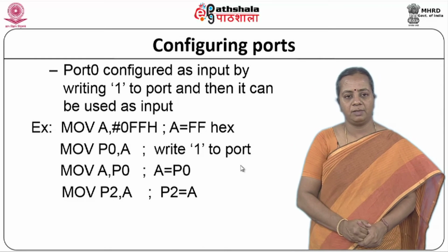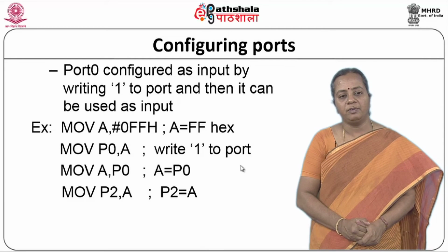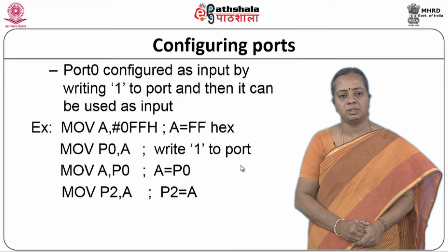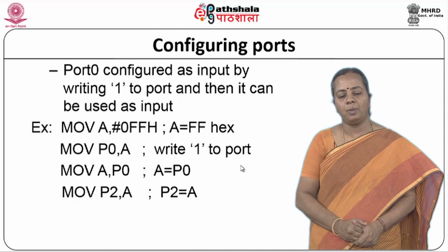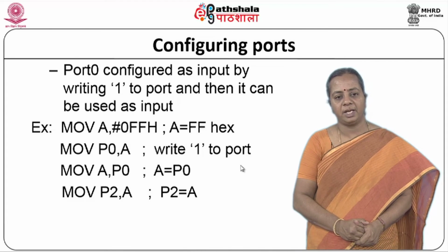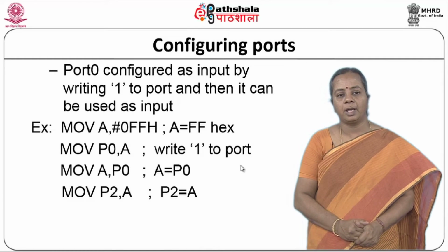If I am sending eight ones, then that particular port will be configured as an input port. Now this simple code gives you: first, MOV A, #0FFH. What I am trying to say is this FF is immediate data, hexadecimal data, which is sent to your A.